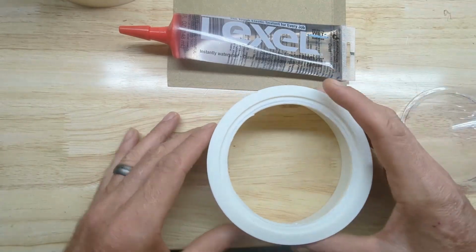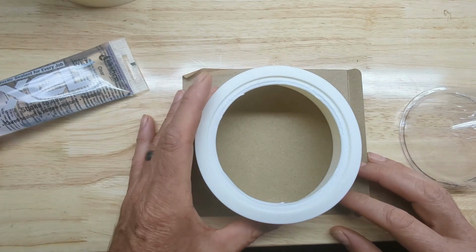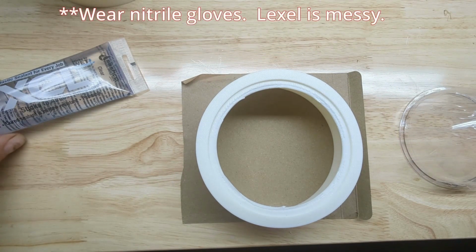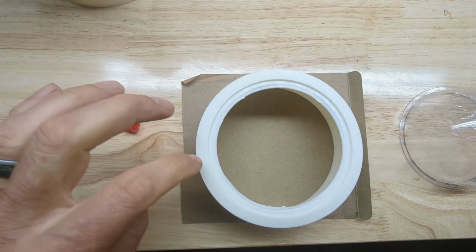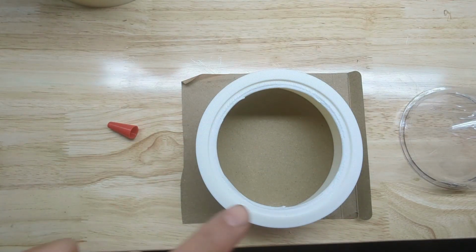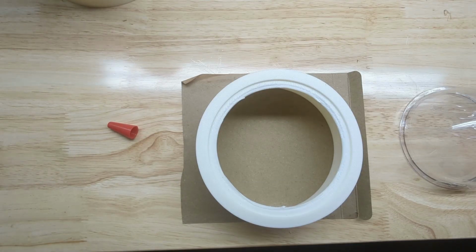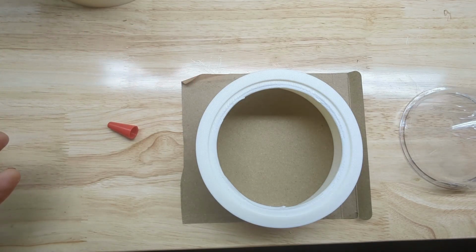So what we're going to do first, this Lexel is very sticky and messy, so definitely put your cap onto some type of table cover. You don't want to get this on your kitchen table or your workbench. What we're going to do is just apply a thin bead around the edge of this, and then we'll take our dome cap and seat it on there. Once it's seated, try not to move it. Let it start curing. Just set it off to the side and let it cure for several hours. I would even recommend not putting it on the body of the enclosure yet. Just give it a day before you do any kind of touching on it.